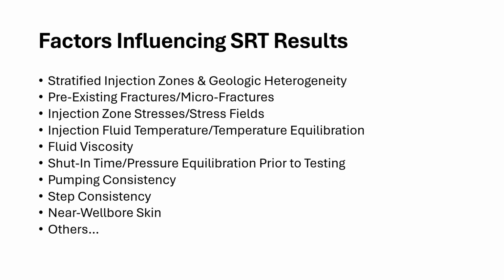Another thing that can occur is that the viscosity and density of the step rate test fluid used may be different from what is in the wellbore, and that can have effects on the early time of the test. Or if fluid viscosity and density are different in different parts of the test, that can have an effect on the hydrostatic density column. The shut-in time, pressure equilibration prior to testing, is important. That's why the states are requiring you to shut in 48 hours, or 24 hours, before testing.